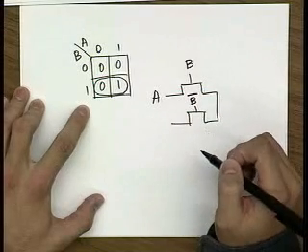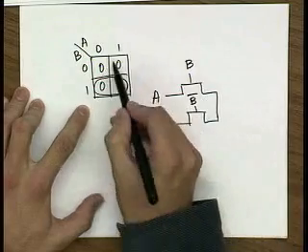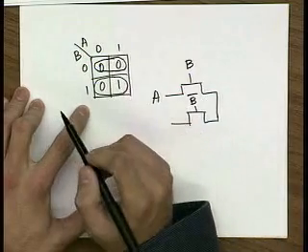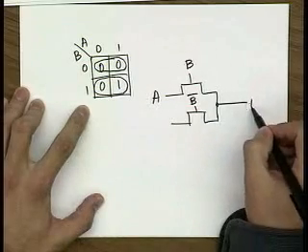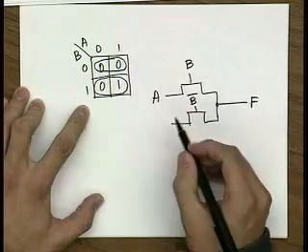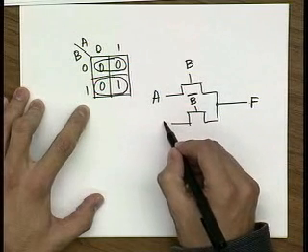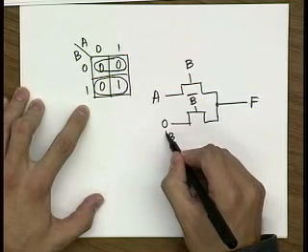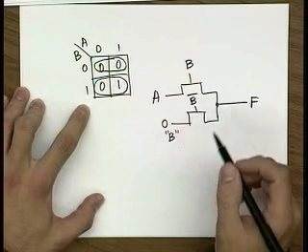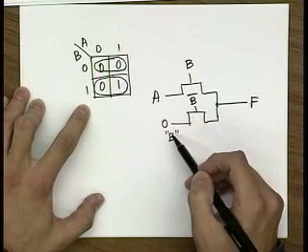And when B is equal to 0, I have to turn on this branch with B bar, and then I'm covering this region of the map. So I have full coverage of the function, and I can put 0 over here. Or I can also put the value of B for that sake, because when B bar is equal to 1, B is equal to 0.